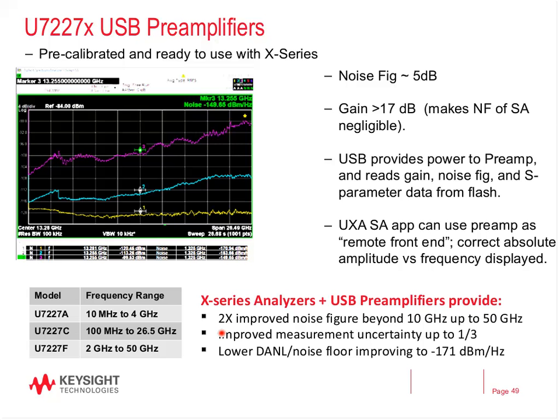But the big bonus here is you get up to 2 times improvement in the noise figure of the spectrum analyzer, which can help you not only improve your absolute noise floor, but also improve your measurement uncertainties. And so that's a nice new tool that wasn't available previously.